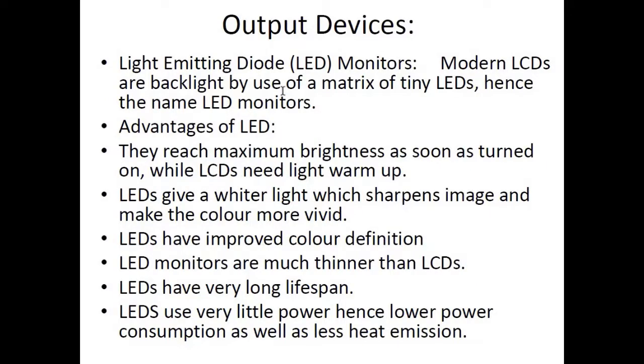Now the updated version of LCDs are LED monitors, light emitting diode monitors. LCDs are backlit. Modern LCD monitors are backlit by a matrix of tiny LEDs, hence the name LED monitors. What are the advantages of LEDs? They reach maximum brightness as soon as they are turned on, while LCDs need a slight warm up, because CCFL lamps need a few seconds to reach full intensity.